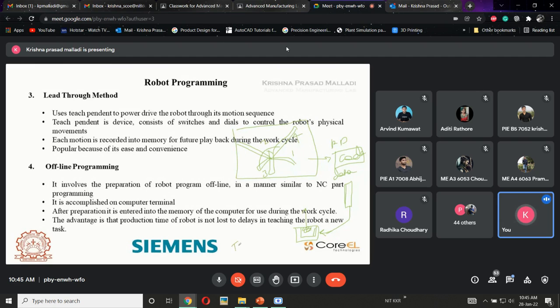In technical language we call it a test run or dry run. The program we obtained from the robot post process software will be tested without having any tool. It will be testing the given motion. The robot will try to reach every location in a controlled manner. If I have defined some 1 kmph speed, it won't follow that in the test run; it will reach with some 0.1 or 0.05 speed, so that we can detect the motion and predict the next motion.